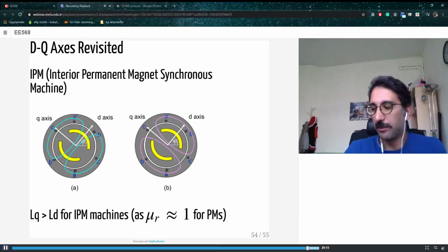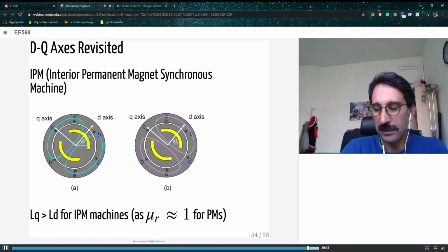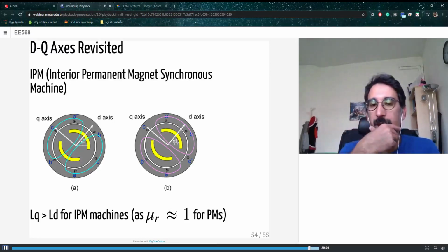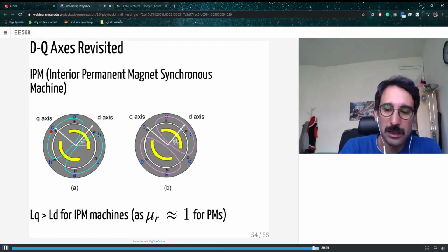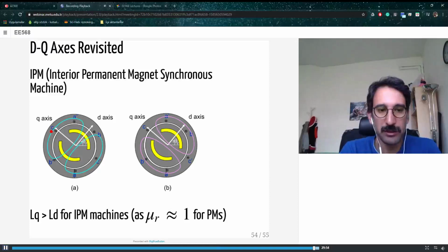These are mainly preferred where weight or torque density is important, like automotive applications. Most electric cars use that kind of IPM motor structure, as do aerospace applications. However, if you don't design it properly, you can generate some positive torque from the synchronous part, but some negative torque from the reluctance torque. So instead of adding up to your overall torque, it will behave like a brake, and it can make your performance even worse.